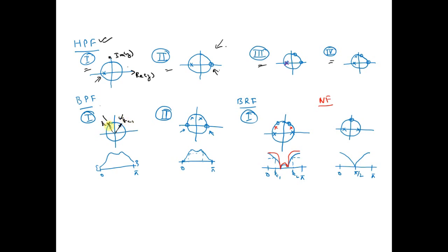You have to find out the FC1 and FC2 through the radius. So that point and radius, wherever they are meeting, you have to find out the frequency point using that radius. The angle over here will be giving you the actual frequency point, the angle and the sampling frequency Fs.